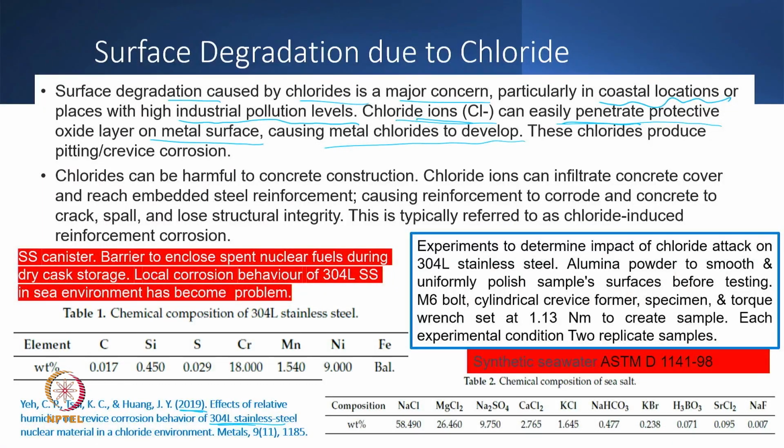So, it is not a protection. After that, the complete system is changing from a protective environment to a corrosive environment. Naturally, the damage will be very high, and we need to consider it from that point of view, and that is why we say that chloride produces pitting corrosion or crevice corrosion. Crevice corrosion is important, and pitting corrosion also, maybe depending on the material, situation, additional circumstances, or location; those things will change.